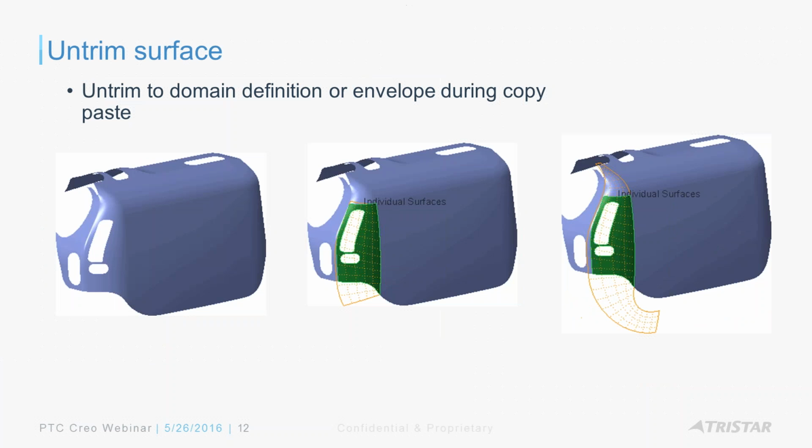So it's really helpful, and you just do a copy paste on that surface patch and you get the option to untrim it, right? And then you can start tweaking that as required, or even use a style curve and then start adding additional control on this.